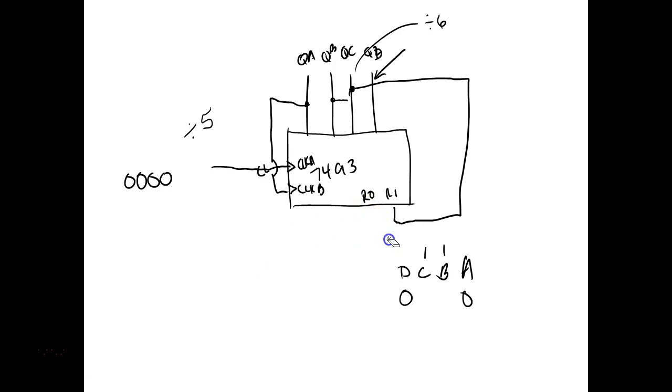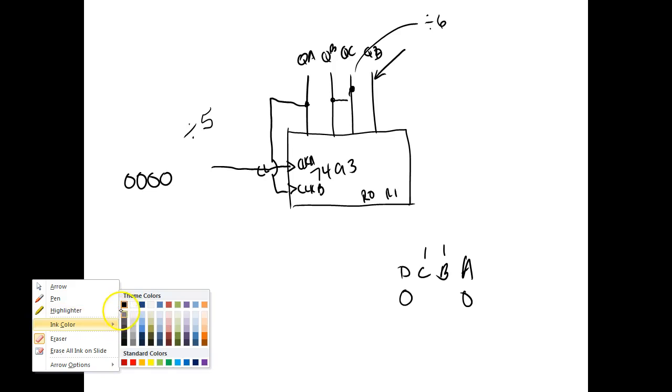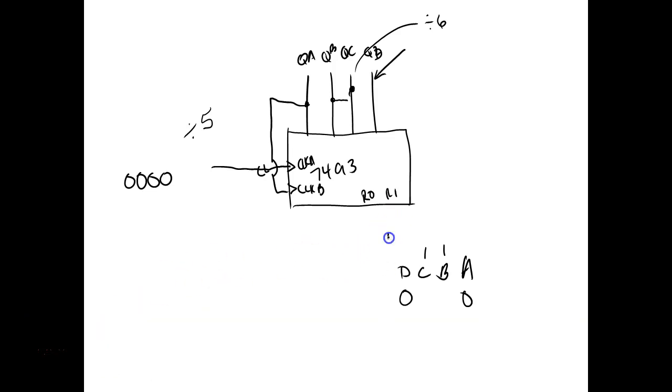Does that make sense? So I've got 2. What I could do, if I needed to divide on these things that need 3 inputs, then I would put another AND gate out here. And then I would bring this into one right there, and now I can monitor 3 inputs, which is the most you'll ever monitor, right? You understand that? So now I can get any division ratio out of a 7493 from 0 to 16. I'm sorry, from 2 to 16.